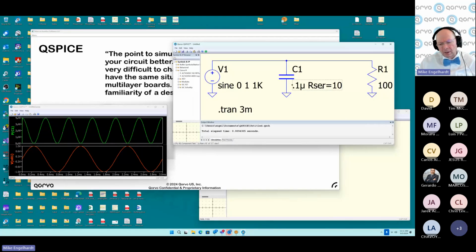So in QSPICE, I've gone through all the device equations of diodes and transistors and reactances and their parasitic impedances, and I actually differentiate displacement currents with voltage drops from actual real currents and voltage drops. So I actually plot the true dissipation. So that's how you do that. There's some compute overhead in doing that, so it's turned off by default.